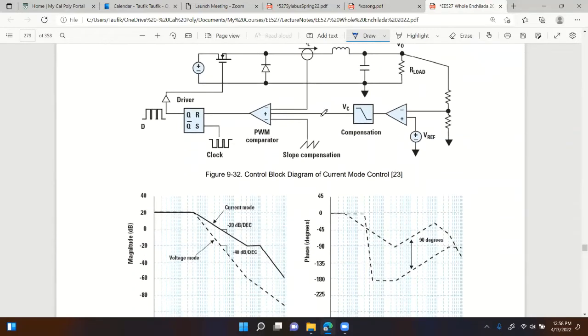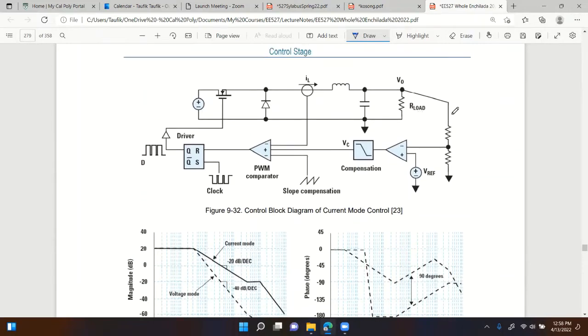That's the block diagram, a simplified circuit diagram of current mode control. You can see the output voltage sensing and the current sensing of the inductor. Again, conceptually, you want to sense the inductor current. The output voltage is compared with the VREF, and then you have the VC output. Remember the constant output. VC sets the limit of the peak, and you compare it with the slope of the inductor current. Notice that there is another input. You see this? There's another input.